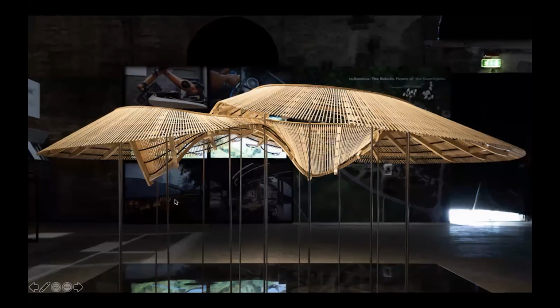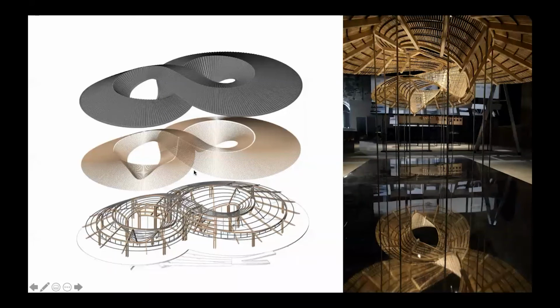Actually, the on-site work is only 48 days because everything was prefabricated in Shanghai. We transported all the components by 6 big trucks to the site, and the workers just put them together, the timber and also steel structures. This is the architectonics analysis showing columns, beams, the roofs, small beams and the tiles. And from the bottom, you can see the whole geometry here.